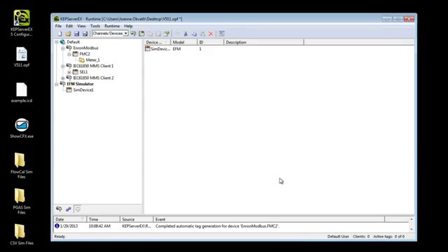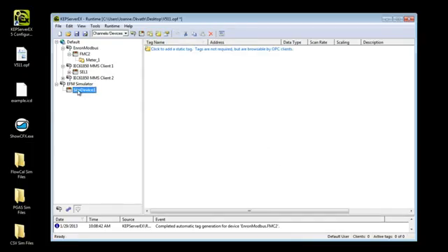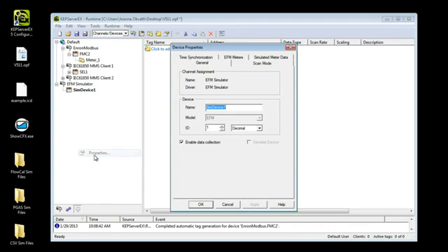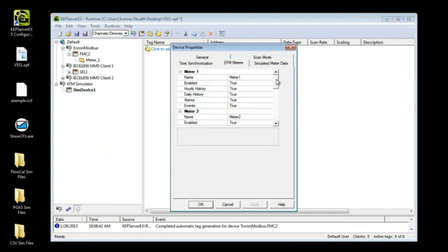Simply create a channel, device, and meter using the EFM simulator and generate data that can be exported by the EFM exporter plugin. To start simulating EFM data, enable meters in the EFM meters tab in the device properties window. Users have the ability to give a unique name to each meter, turn it on and off, and control what kind of data will be generated in the simulated file.